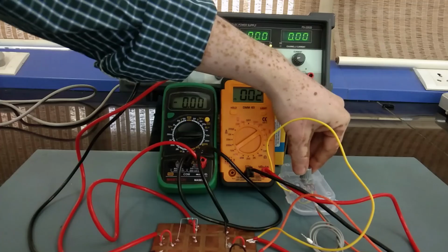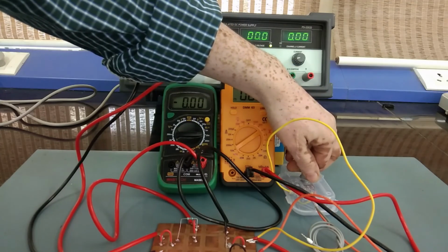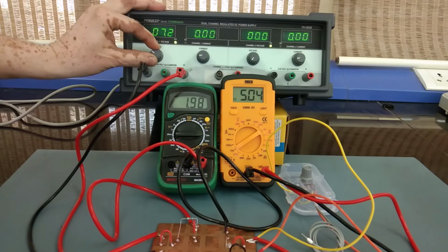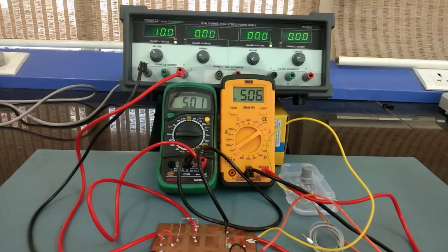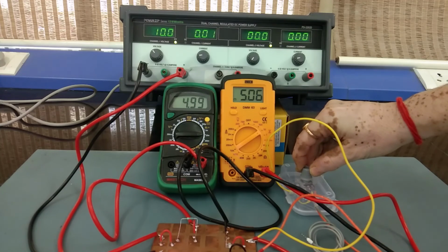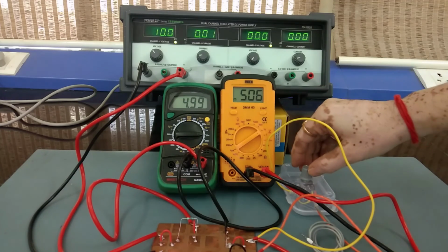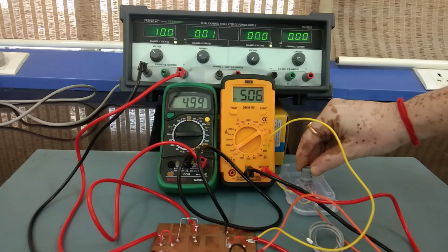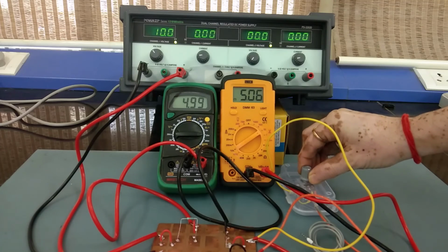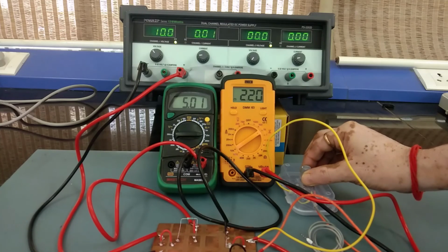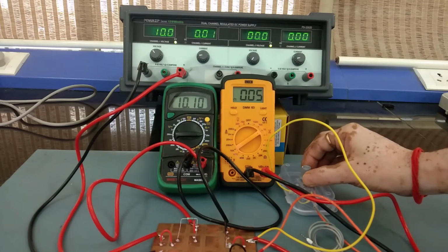Now what I will do, I will keep some voltage constant above the value of 5.1. Maybe I will keep 10 volt constant, and then I will be changing the value of load slowly. We have to check whether there is any change in the output voltage across the Zener. You can see I am changing the load. You kindly look at this white spot. Okay, now it's shorted actually.